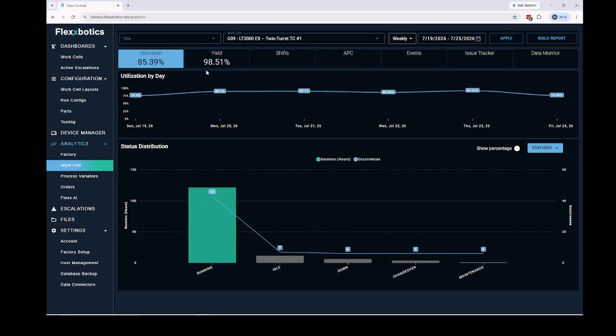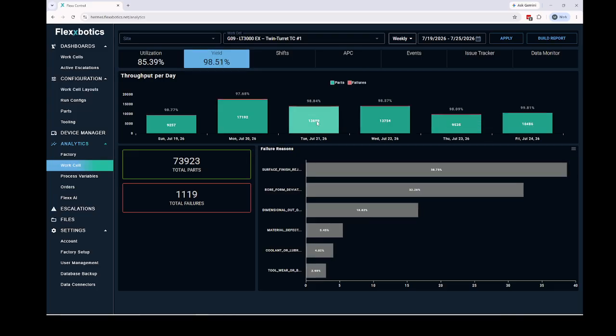Notice that in both views, we're using contextualized data to drive specific downtime reasons and failure modes. These results are composited from multiple variables and machine feedback as well that are processed by the system transformer. For example, we can highlight that a reject was being caused by oversized stock based on both robotic gripper feedback and machine probing. Or perhaps we can identify when a machine has a coolant failure, not from a specific machine alarm, but by noting coolant pressure dipping for more than 10 minutes.